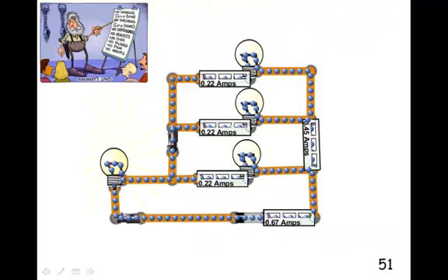So then I put ammeters in, and here was our total current, that 0.675 it should have been. And then that 0.675 branches off to 0.22. It should have been 0.225 here, which it's just truncating. And then this is 0.225, and this is 0.225.